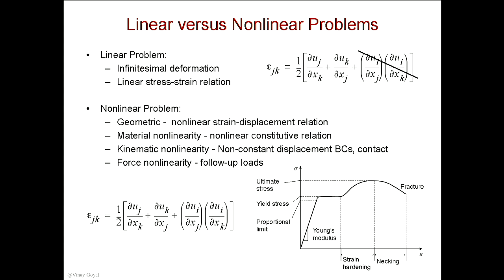So for nonlinear finite elements, typically in a linear problem, the full Green-Lagrange strain tensor has 6 components that include the higher order terms. But for the linear problem, these higher order terms are neglected. This can be done when you have small displacements, small gradients, small rotations. In Abaqus, for example, if you turn NLGEOM off in the step definition, star step, comma, NLGEOM, it's going to use small strain approximations.